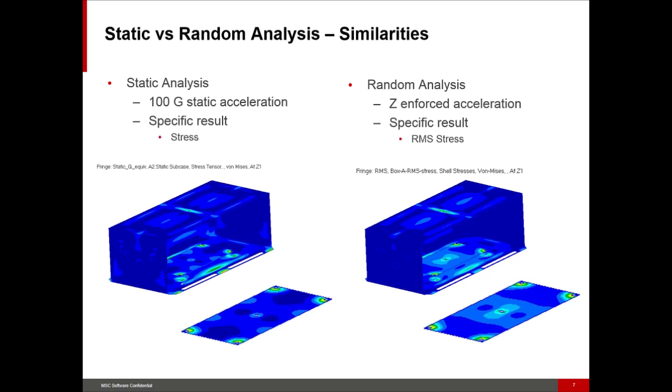Again, we do see the same general trends as we looked at in the displacement, where we have our bolt holes for that circuit board. We do see higher stresses in the corners and at the center. But if we look a little bit closer, we're starting to see some differences of where the higher stresses are, not necessarily the very high loads for the connections, but the other general parts of the structure are starting to differ. So this is where our static analysis that we perform, it's pretty close.